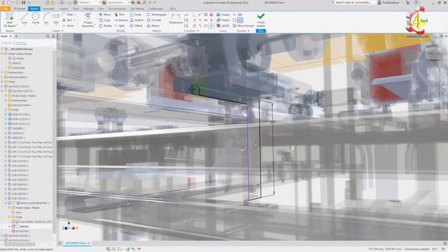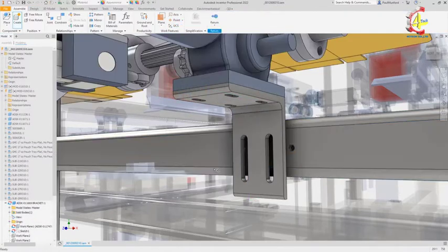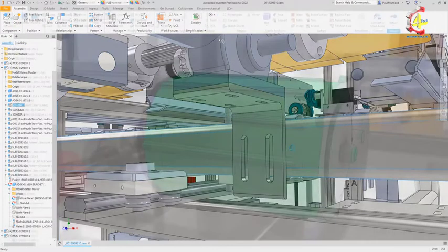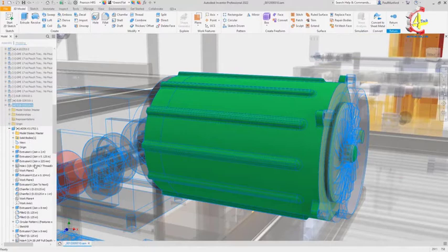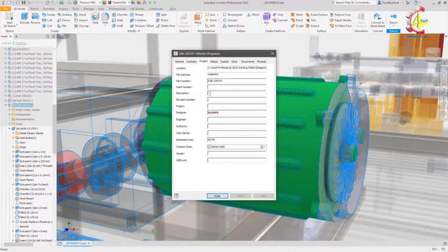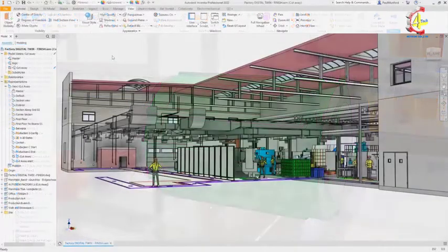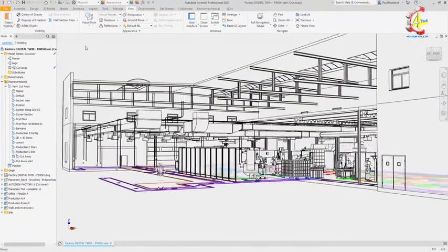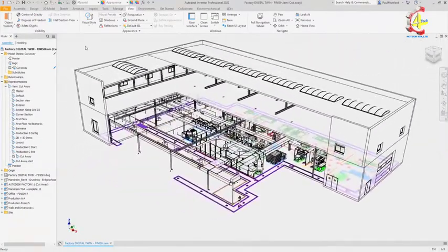You'll notice that when object visibility is off, only newly created sketches and work features show during feature creation. When editing in place, you'll notice that editing eye properties is now possible for all components in the assembly, not just the components you're working on. What you see on the screen has also improved performance, specifically with view orientation, panning, and zooming.